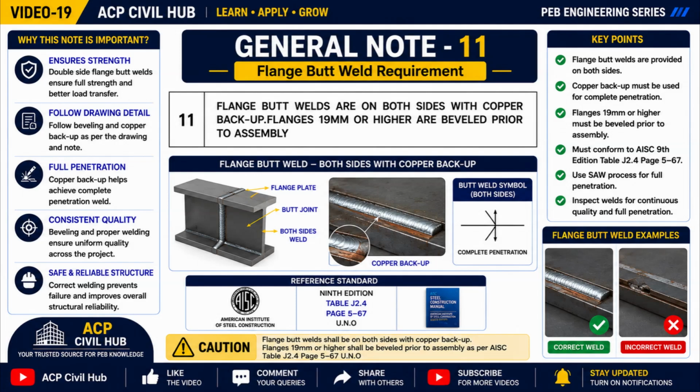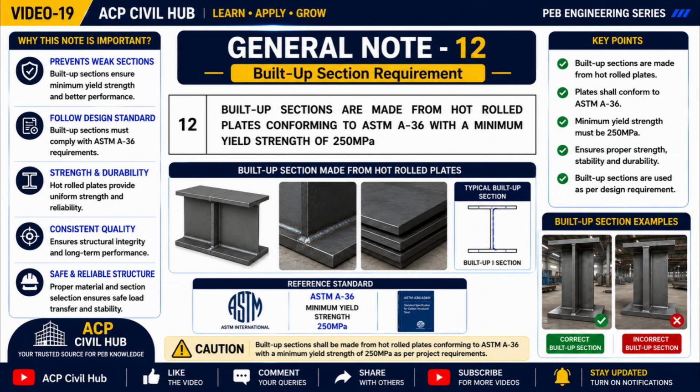Proper edge preparation, correct welding procedures, and thorough inspection are essential to ensure the joint meets the required structural performance and complies with the project specifications. General note number 12 explains the material requirement for built-up steel sections used in a PEB structure.